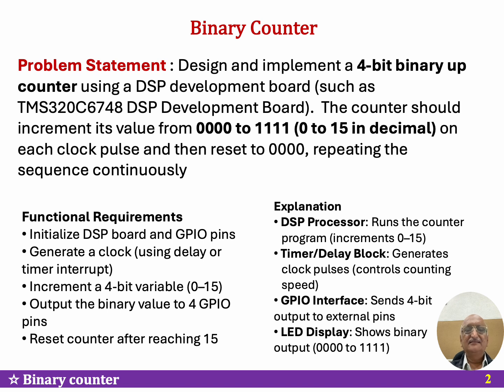Here the DSP processor runs the counter program, timer and delay block generates clock pulses, GPIO interface outputs to external pins, and LED display shows the output from 0000 to 1111.